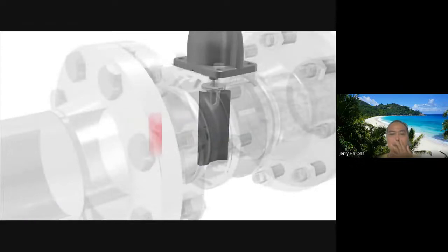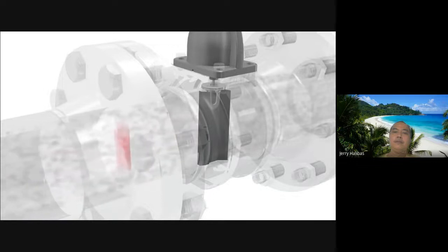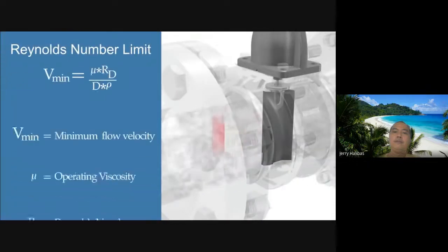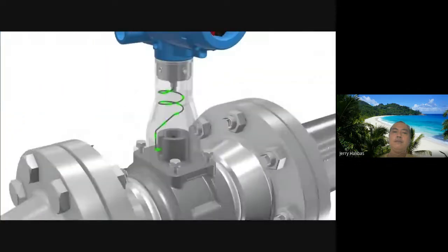Because vortices must form in order for the vortex technology to pick up a signal, an adequate ratio of inertial forces to viscous forces must exist. If not, the meter will read no flow when the fluid is flowing. Once a mechanical signal has been formed by the vortices passing by the shedder bar, a sensing element takes the mechanical motion generated by the flexure and converts it into an electrical signal.